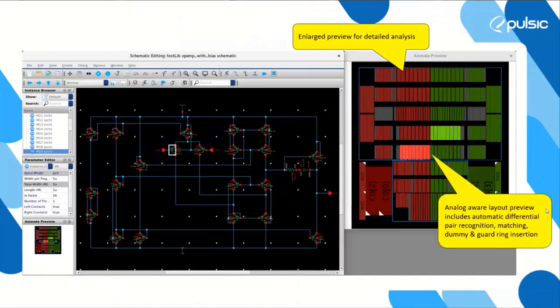It's really analog aware. It is analyzing your circuit. It's recognizing the differential pairs and the current mirrors. It knows about wells and making them LVS correct and putting the devices in the correct wells and drawing the guard rings and matching and everything else. And in fact, in this design here, you can see the red and green are showing left-right symmetry in our op-amp type design here.